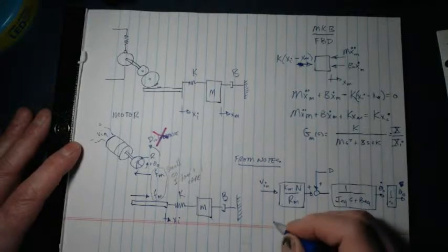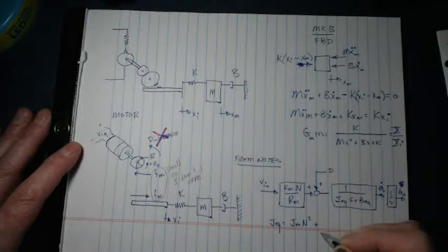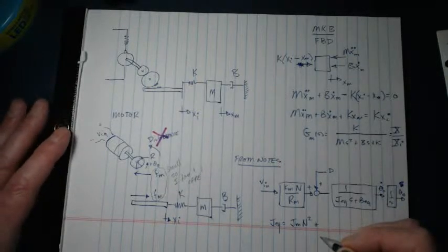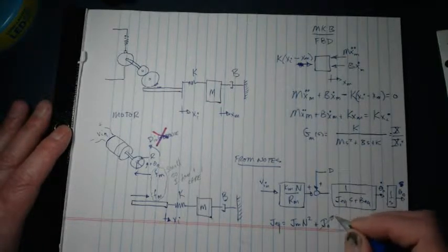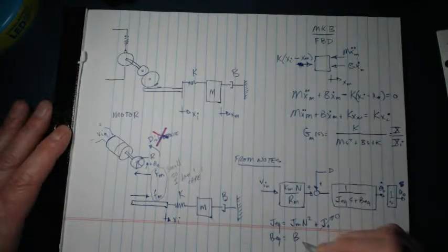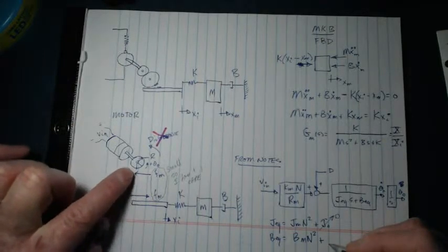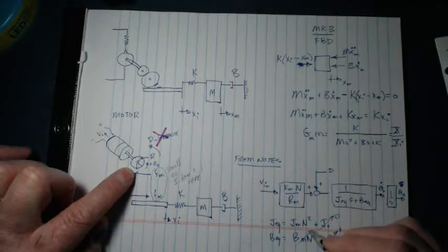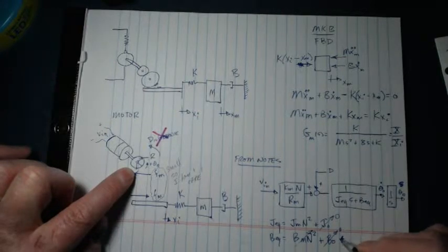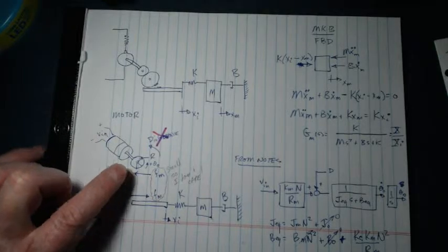We've used it before. And what we know is that J equivalent is equal to the motor inertia times the gear ratio squared. We'll get that from the manufacturer. If there's any output inertia, in this case we're not going to have any, we'll just leave that to be 0. We know that B equivalent is the motor damping times n squared, plus any damping at the output, and again, I'm just going to neglect that for now. But even if we neglect everything on here, there's still the back EMF, which is the back EMF constant, the motor torque constant, n squared over the resistance on the motor. So we know that there's a little bit of damping on that thing.